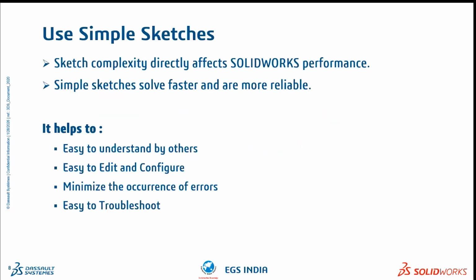First step: one of the most important best practices in SolidWorks is to use simple sketches. Sketch complexity has a different impact on performance. Simpler sketches solve faster and behave more reliably. They are easier for others to understand and much simpler to edit or configure as a design evolves. Keeping sketches simple reduces the chances of errors, makes troubleshooting easier, and significantly improves the efficiency of the design process.